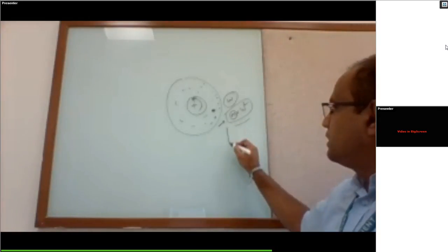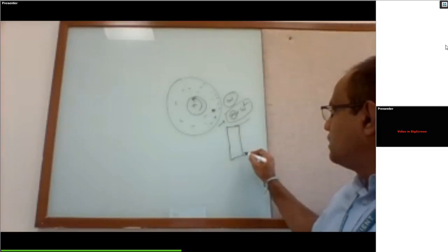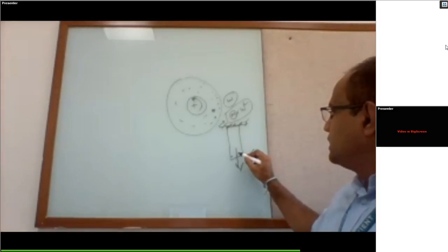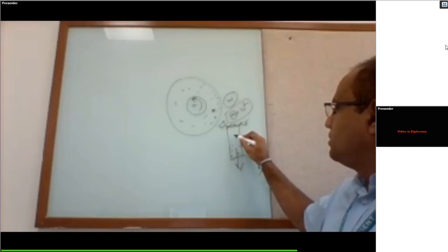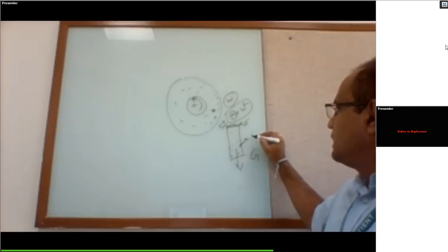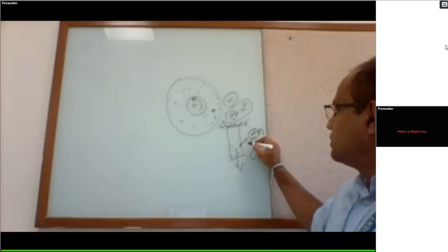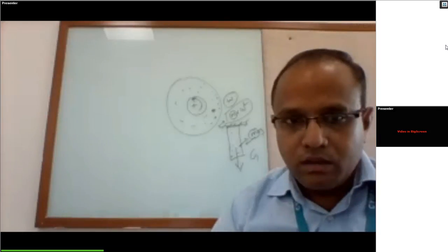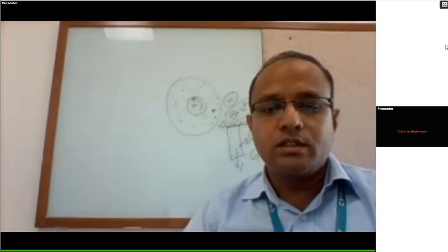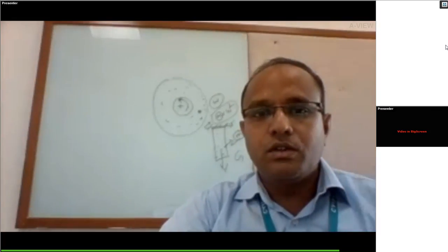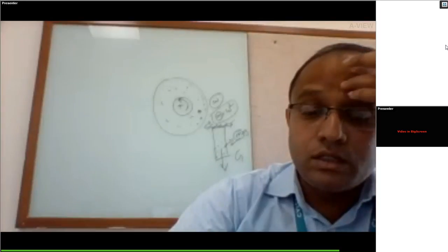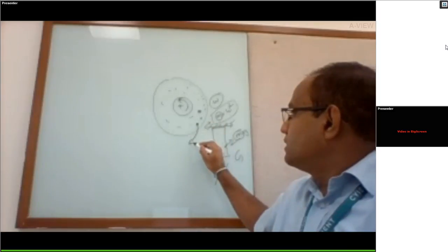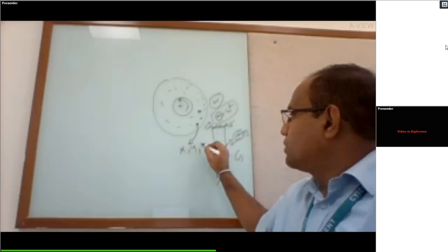Similarly, suppose a bar is subjected to gravity load. Each node in the bar will be subjected to gravity load, that is m into g, where m is the mass of each node. So typically body forces consist of centrifugal forces, for angular velocity, and gravitational forces. Since it is a point rate, it depends upon the x, y, z locations of the node.